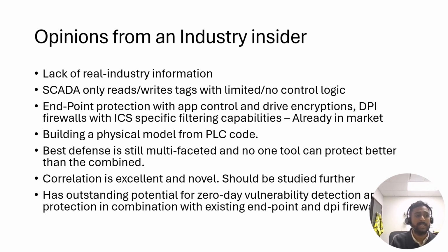But that said, Scaphy would have successfully detected the infamous Stuxnet attack, which used legitimate Siemens software. It used a bug in that software, but Scaphy would have recognized it because it can see OPC browse as a separate state. That's the initialization state. However, I think this attack would have also been identified by a combination of deep packet inspection firewalls and/or any modern application control capable endpoint protection software.